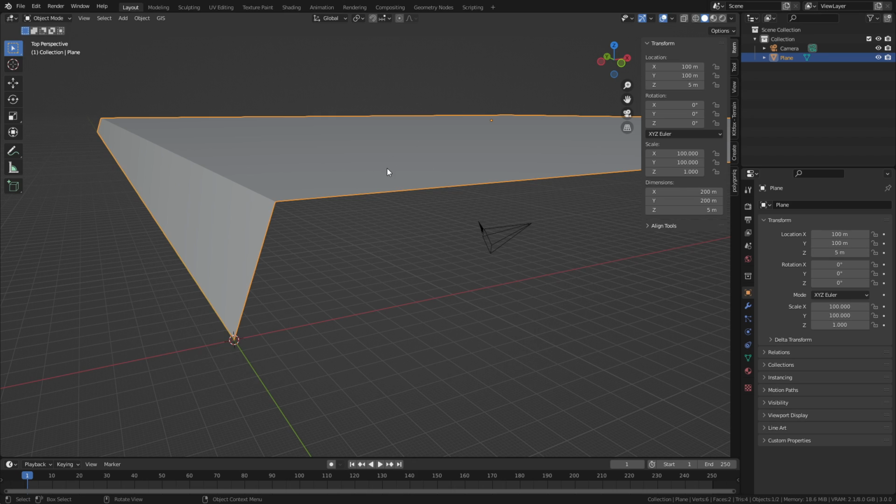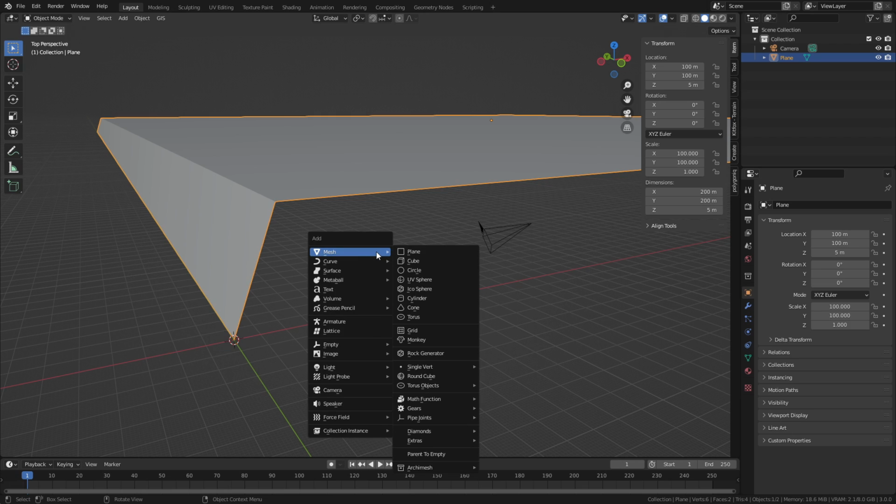So 5 meters in Imperial, roughly, that's going to be 15 feet. I have 15 feet to deform down to this, or to sculpt my terrain to go lower than this plane right here. You can pick any number you want. I could have picked 100 meters. Doesn't matter. The thing that matters is this is our 0 point. We're not going to be riding over here, and this is above it, so we get good deformation in the game.